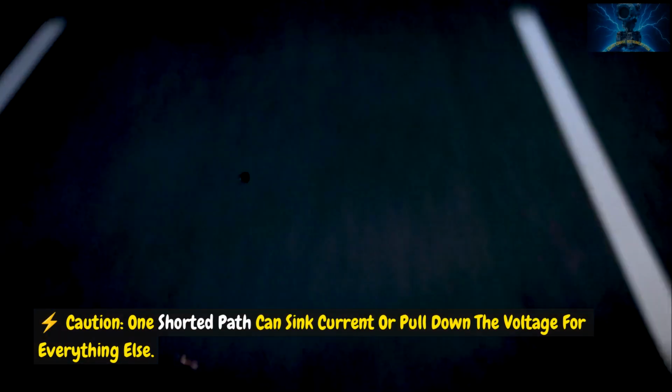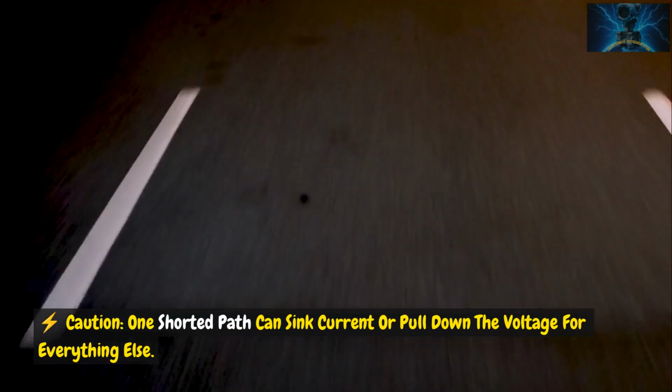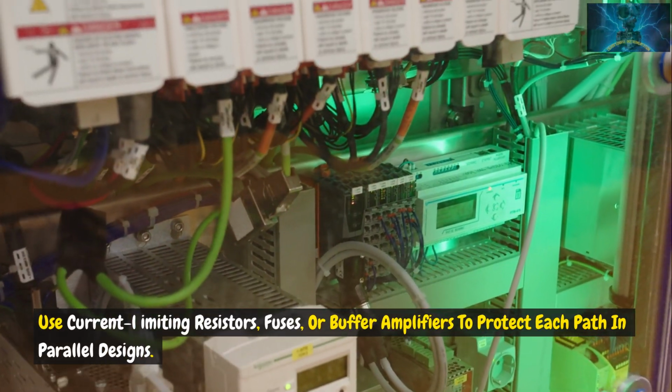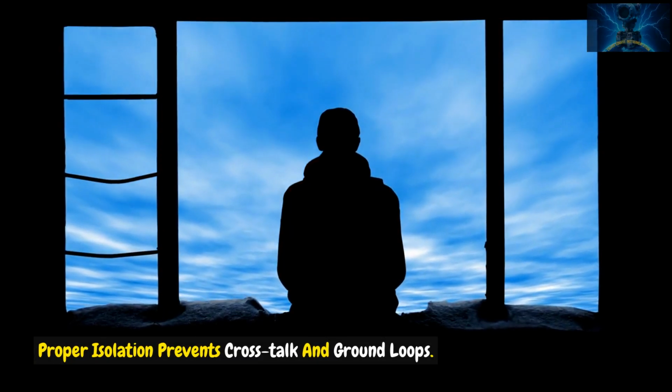Caution: one shorted path can sink current or pull down the voltage for everything else. Design tip: use current-limiting resistors, fuses, or buffer amplifiers to protect each path in parallel designs. Proper isolation prevents crosstalk and ground loops.